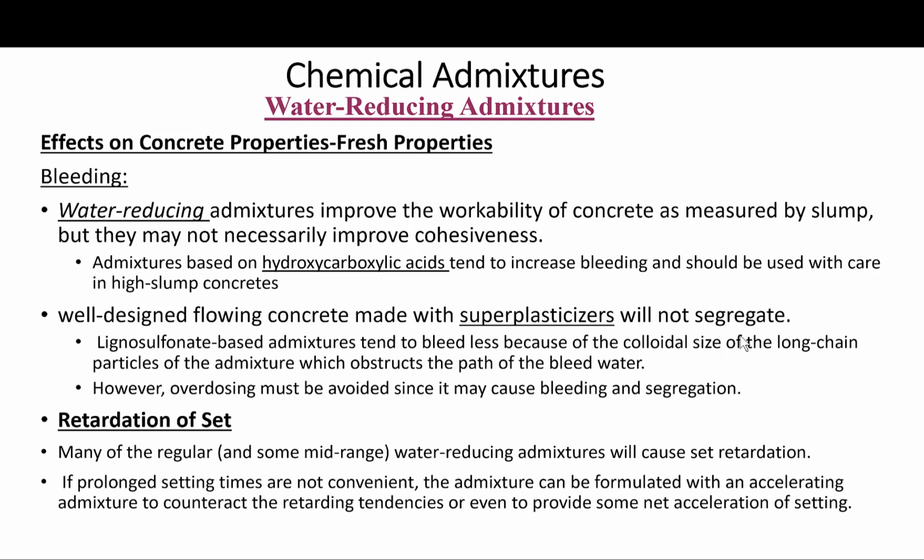However, non-retarding formulations sometimes show a tendency to cause retardation at low curing temperature. It has been found that delaying the addition of the admixture until a few minutes after water has first been added will increase the potential water reduction, enhance air entrainment, and also increase the retardation of the set, if this occurs in regular additions.